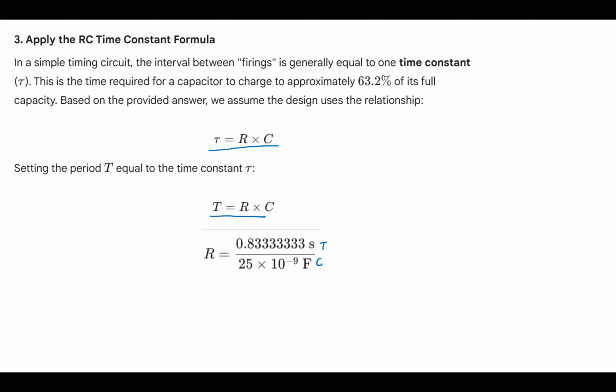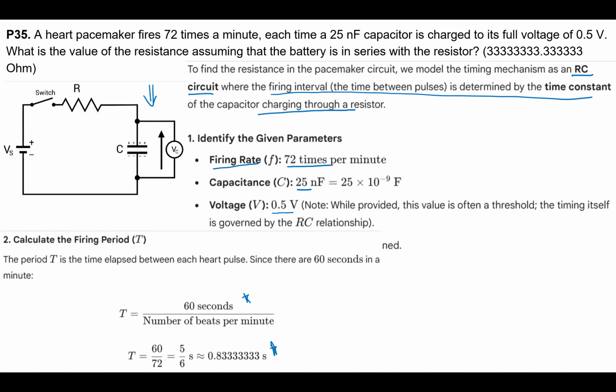Okay, and then if you discharge, once again, RC comes in as a time constant, so it is absolutely important to know that the time constant in this RC circuit is determined by R times C, whether charging or discharging.